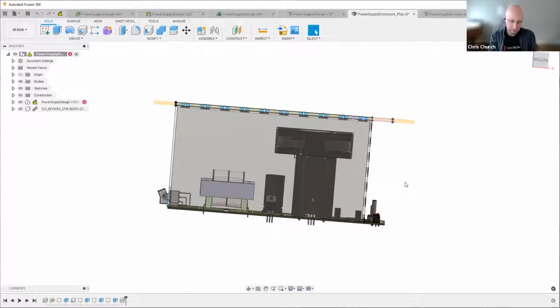And one of the questions our team would have for you is, what is the look and feel you're going for here? Are you going for a real clean outside look? Do you want to minimize any possible user interference? If so, we'd want those screws to come up from the bottom of the fan into the enclosure itself. And so we would work with the enclosure manufacturer to add threaded inserts at those locations.